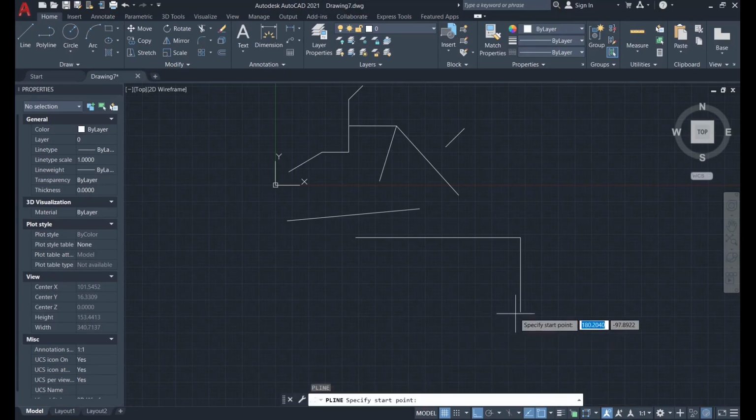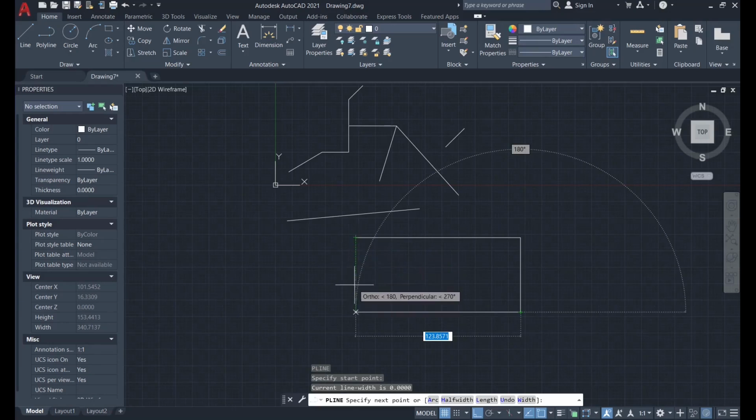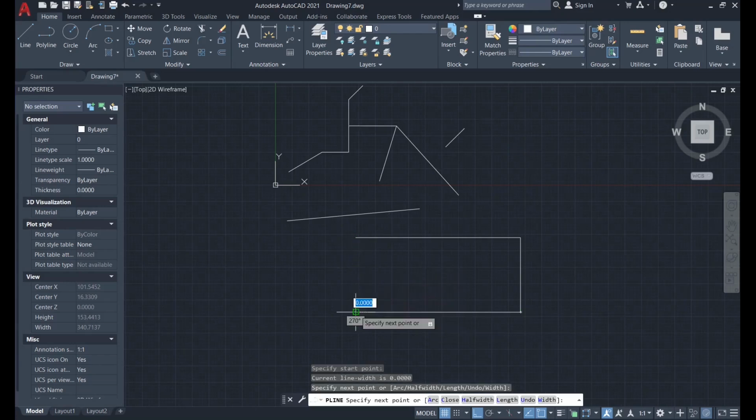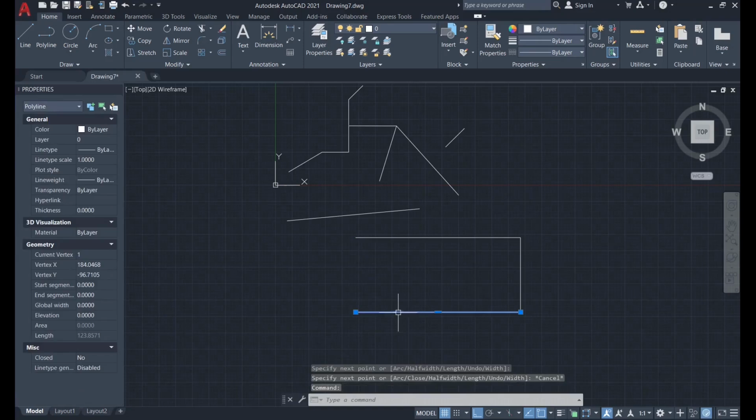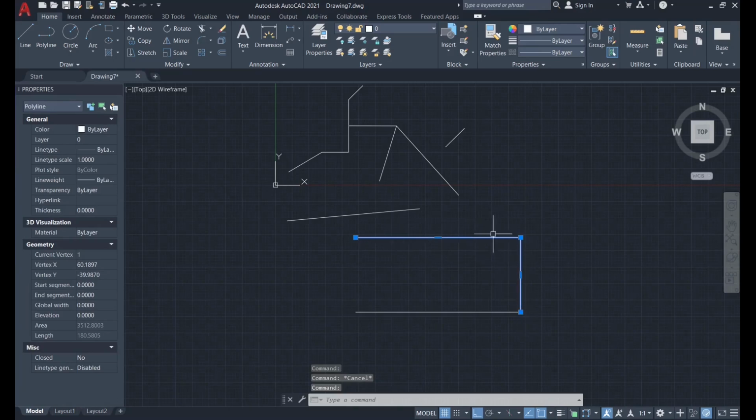So as you may see on the screen, I'm using the polyline. I go to the endpoint of the above polyline and now it shows me where it ends by this green axis. So if I click it, I know that both polylines have the same length, but it calculates the length of both segments.